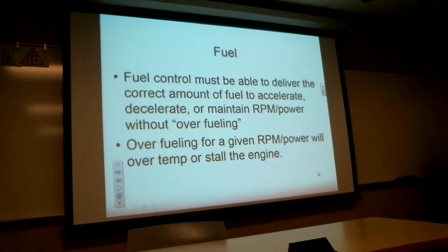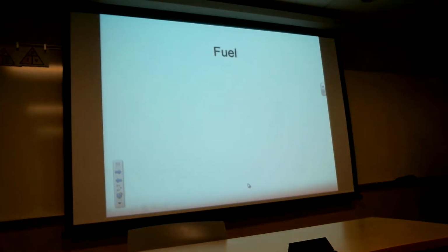He had to turn out of line and go back to the gate because now he's got an overtemp inspection that has to be completed on the engine. So don't you just know those people were not real happy about that. This kind of stuff happens from time to time, not real often, but it does happen. Overfueling an engine is going to cost you an inspection because they have to go in with the borescope and make sure that you didn't melt something inside the engine. And of course I thought it was funny that, hell, we moved up in position instantly.